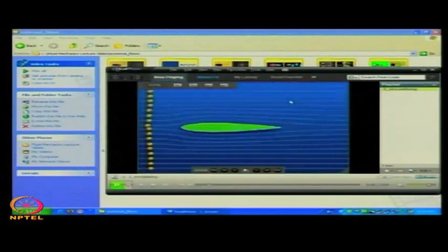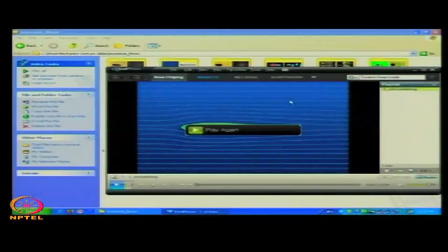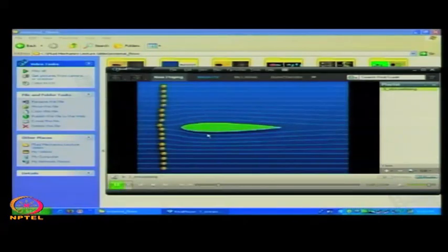Let us have a shape like this. If you see now, this is such a shape where the boundary layer separation is almost avoided. It of course depends on the direction of the relative velocity between the solid and the fluid, and that we will see, but you can see that the section is such that it is not blunt. The previous bodies were blunt, and those are technically called bluff bodies. This type of shape is called a streamline body.